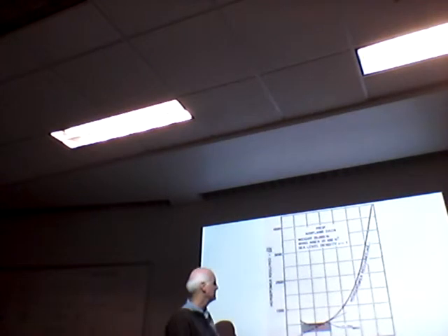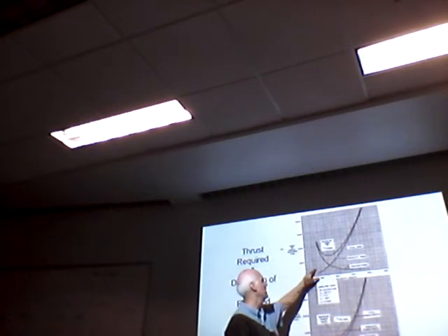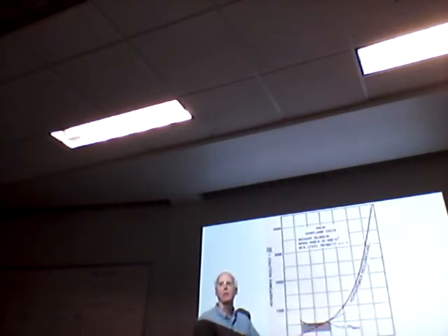I thought I had those. Oh, actually, this isn't. So this is kind of weird. For this airplane, if I start at the origin and I go tangent, that's my best climb rate and all that kind of stuff over here, best range. With a prop aircraft, I do the same thing, and lo and behold, that's actually where L over D max is. It's up here. So now, here is your max glide range, and your max endurance speed, and all those kinds of things. So when you go off the tangent line, it's different between jet and prop.